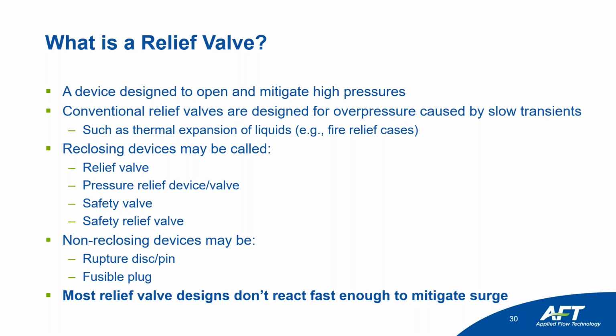Conventionally, you see that these are used for a lot of slow transient type of behaviors. So that might be like thermal expansion of liquids. You find them on boilers often, if gas pressure gets too high, fire relief cases. But you also see them in liquid systems for if pump discharge is blocked, some things like that. So you end up reaching deadhead cases.